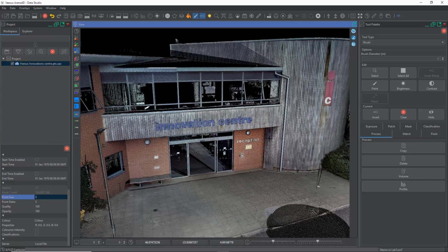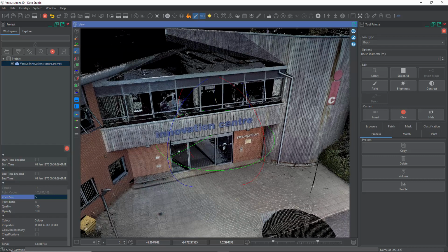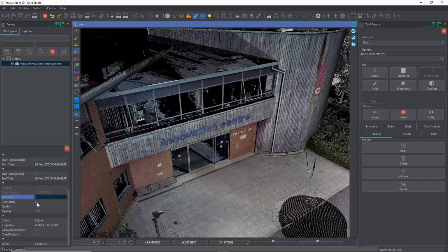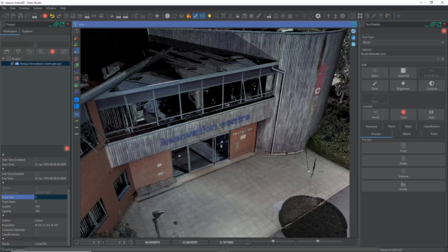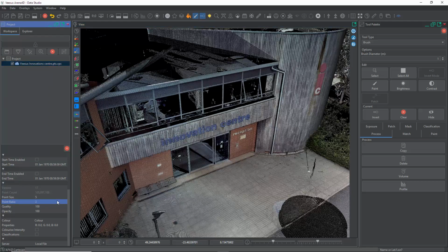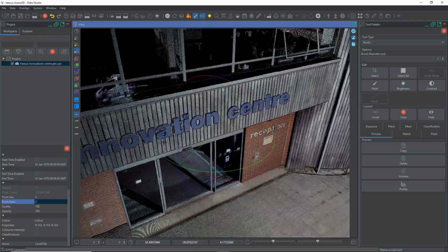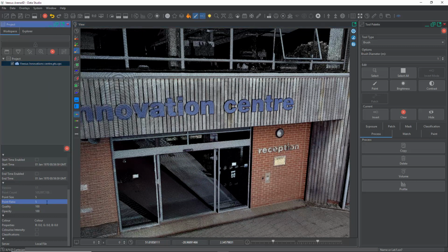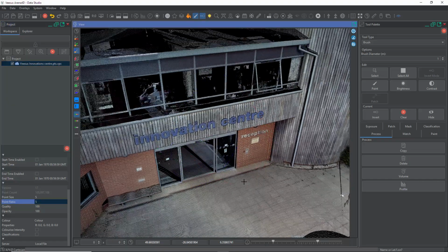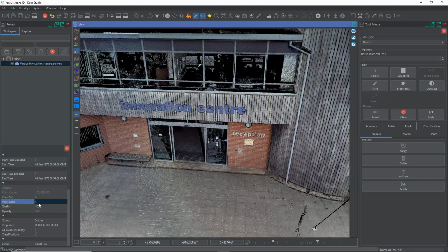These are additional options to the filling and super sampling video you may have seen, but these are the values that get changed. There's also a point ratio, so filling is turned on, which has been mentioned in a previous video and should be turned on generally. The ratio will change as you move point cloud distance in. So again, experiment with your point cloud. The default of 5 generally works the best, but if you did have a point cloud that scanned in a particular way, try changing point ratio with filling turned on.